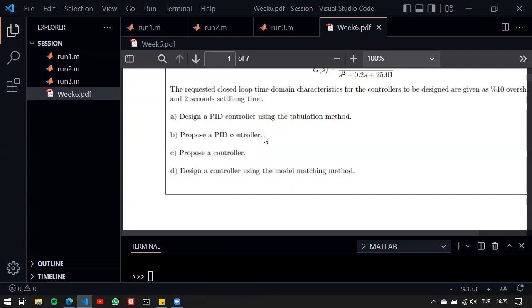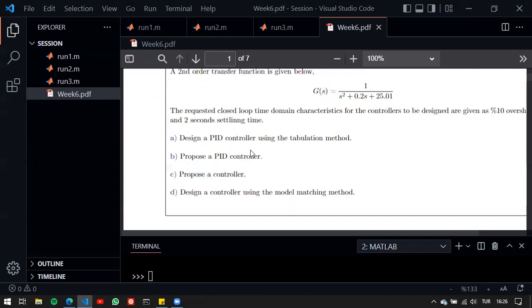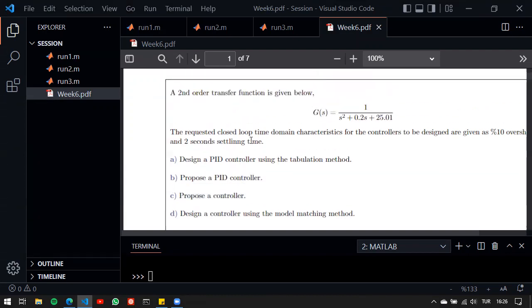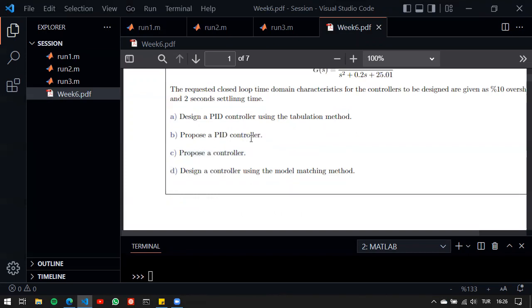Here we have learned from the fact that there are some closed pole and zero pairs. So why not cancel them out? It has some advantages, some disadvantages. So based on B, we've proposed another controller that has one more pole to it, and it just satisfies both the settling time and overshoot values or requirements.